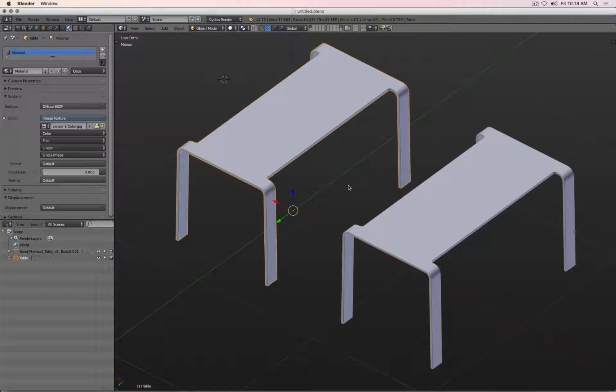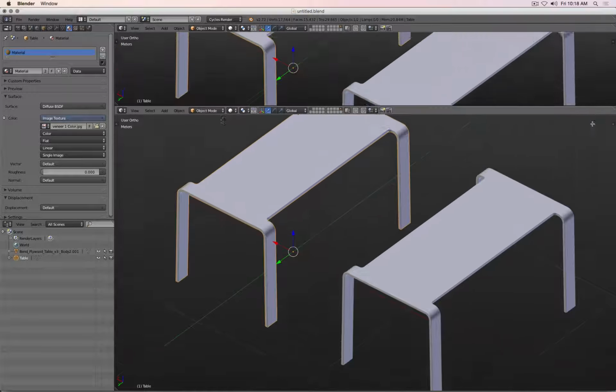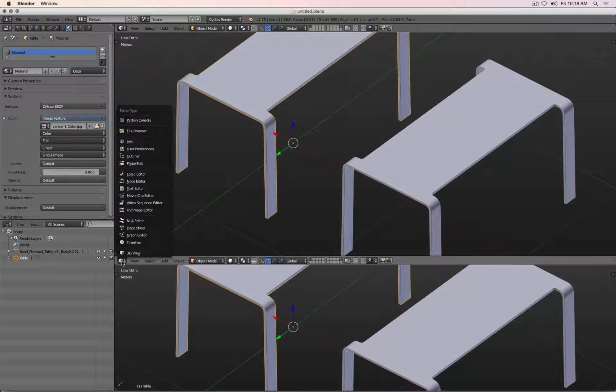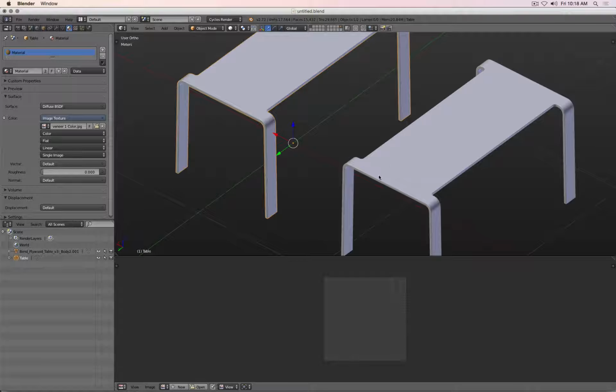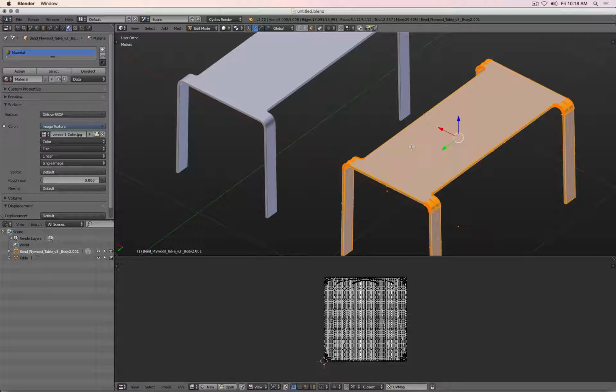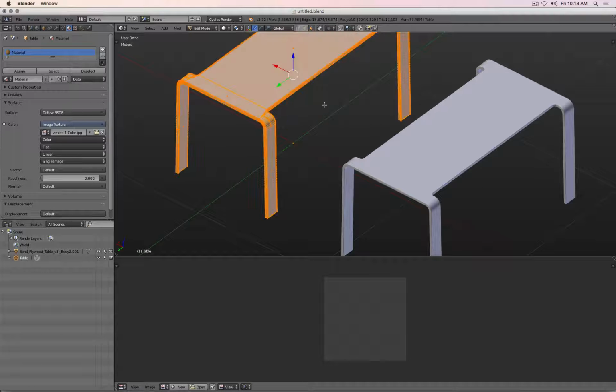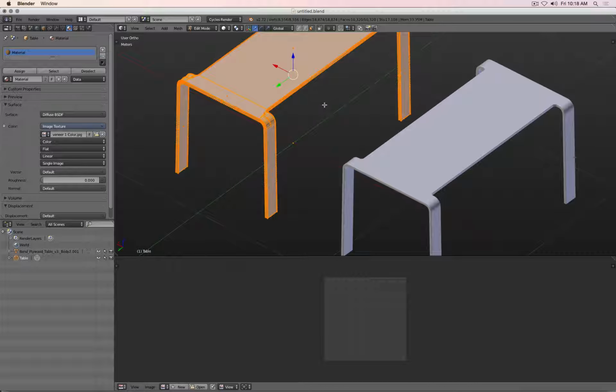The advantage of using OBJ is also that it natively comes with the UV unwrapping. Unfortunately, MOI can actually take the NURBS UV coordinates and basically puts that into the polygon mesh. So if I select my MOI model, click A, there you see everything is UV unwrapped. If I click my STL Fusion import, nothing is unwrapped.